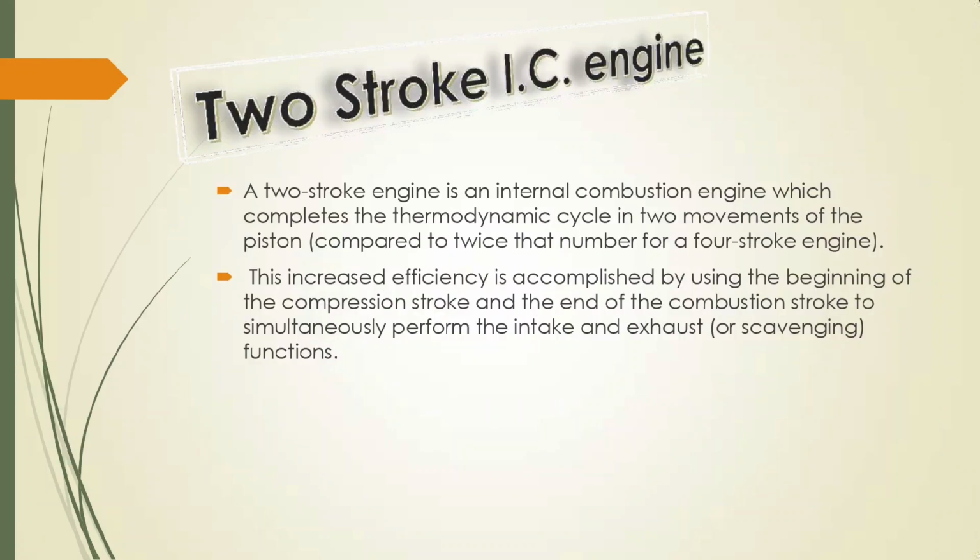Stroke is nothing but the linear distance between the top dead center and bottom dead center. Engines are classified into 2-stroke engines and 4-stroke engines. If 2 strokes are completed by 1 cycle of operation, it is called as 2-stroke engines. If 4 strokes are completed during 1 cycle of operation, these are called as 4-stroke cycle engines.